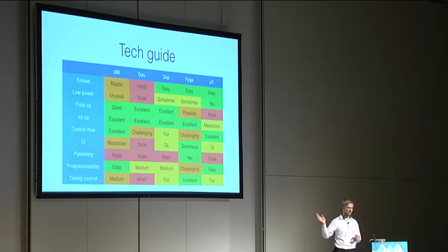And obviously they can do pipelining, which is pretty cool. Well, the programmability is a bit challenging, but if you want to do timing, those are really, really good. You can do really precise timing up to nanosecond level. If you, for example, want to violate the setup and hold time of registers, you can do it with FPGAs. It's pretty cool. There's also a very interesting talk about attacking ICs later at 21:45 in Hall 1, which you should take a look at. It's pretty interesting to see.